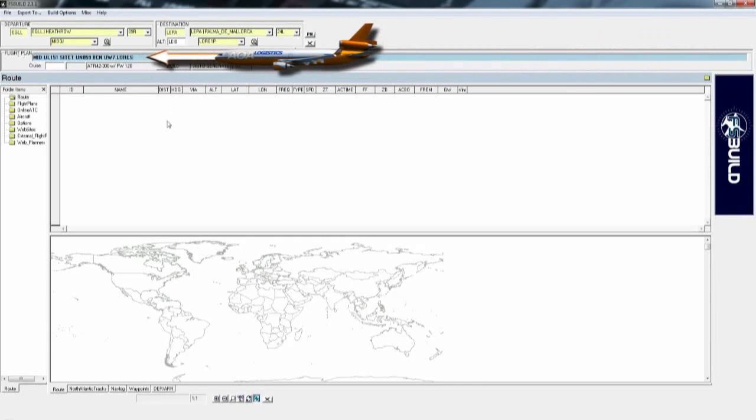Our flight will take us from Heathrow, runway 09R, via the Midhurst 3J SID to the Midhurst VOR, then via Airway UL151 to SITET, Airway UN859 to the Barcelona VOR, then via Airway UW7 to LORES, and finally via the LORES 1P STAR to runway 24L at LEPA, which is Palma.